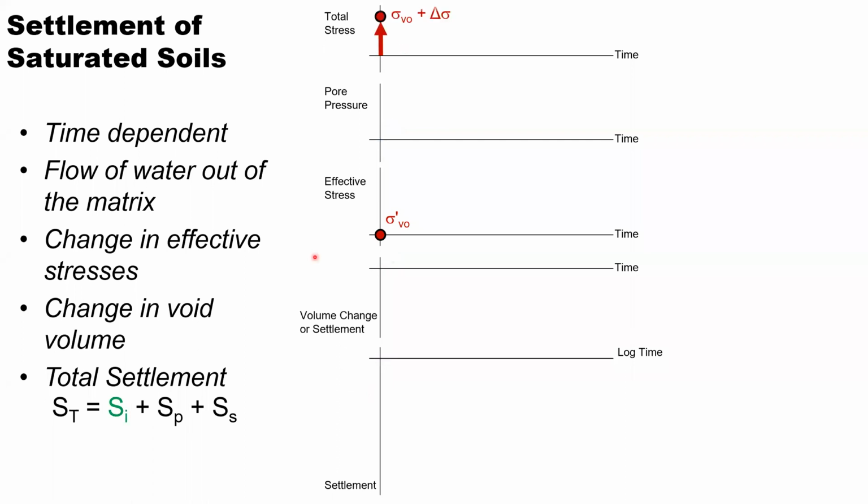Let's add in that change in total stress. So once again, we're adding a new lift of soil, for example. So this is being placed instantly, so I've got this happening over zero time. Of course, that's not terribly realistic. That's idealized too, but for the purposes of this discussion, it should do. In response to that, as I mentioned, because these tailings typically have relatively low permeability, the pore water pressure is going to increase by an amount equal to that change in total stress.